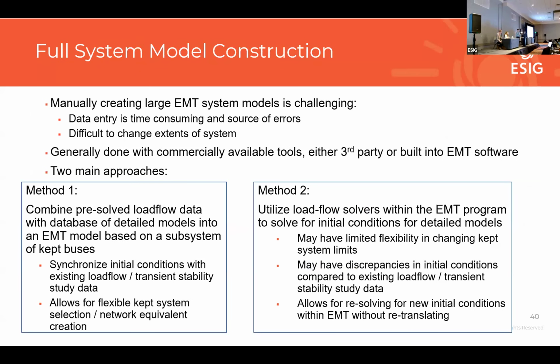All right, so a little bit about how to actually go about constructing the EMT model. We decided this is the area that we want to model in EMT, and these are the detailed models that we want to include in our system. Now, what are the actual mechanics involved in taking these various puzzle pieces that we created and putting them together into a cohesive simulation that we can run? So I should back up. This generally is not done manually. It's a huge effort, and it would take a lot of time to do manually. So this is usually done in an automated manner using commercially available tools.